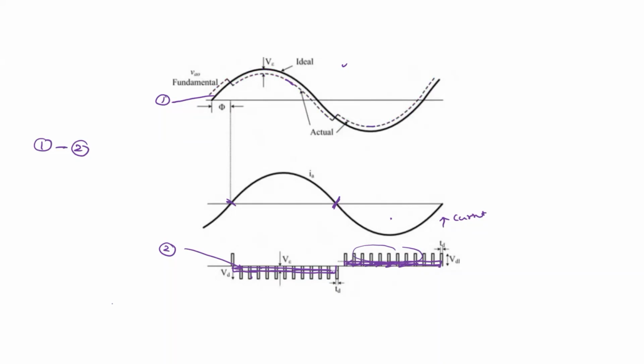Now tell me, is the overall voltage reduced or increased? The overall output voltage is modified, depending on the inverter current. When the inverter current is positive, the output voltage is reduced this much, right? Here also you can notice that the output voltage is reduced. Only during the transitions is there an actual increase in the output voltage.